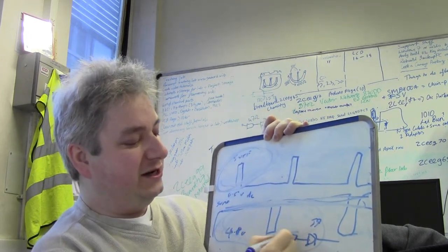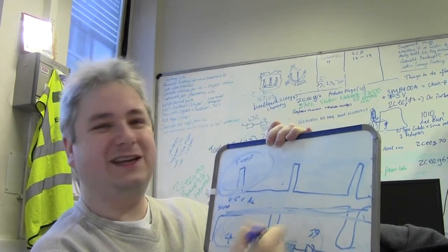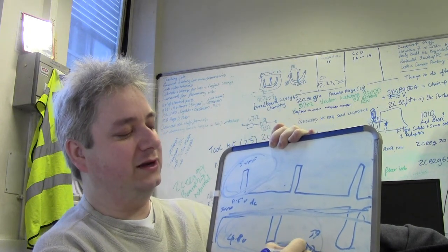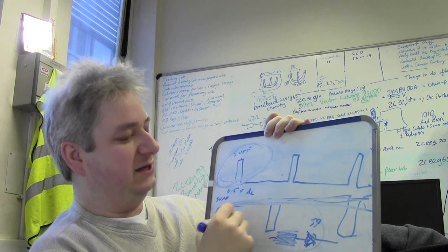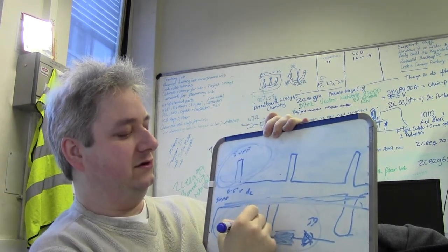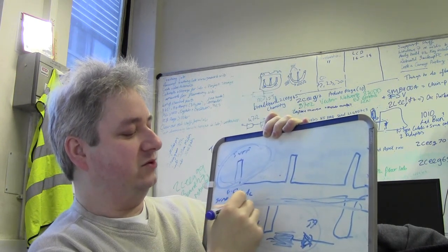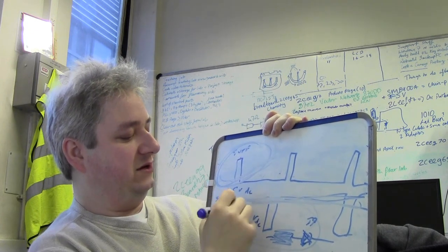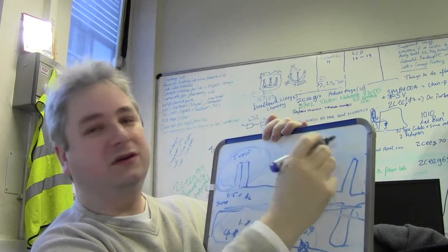Lots of people say no, you don't have to do that, you can get away with it, and with PWM the LED is not receiving full power, so I can ignore that resistor and power it directly. It's perfectly fine if your mark to space ratio isn't going to go above the equivalent of 1.8 volts DC for your LED. So you may only pulse width up to an average of 1.8, so it might only be 30% on.